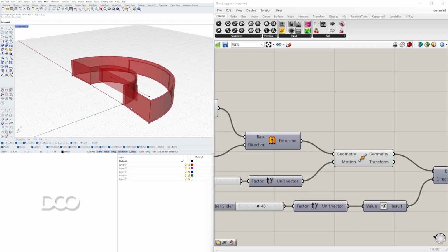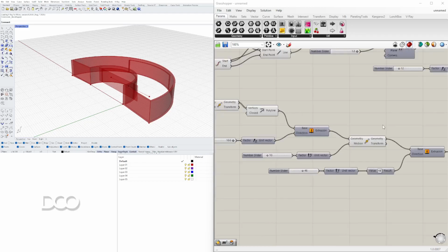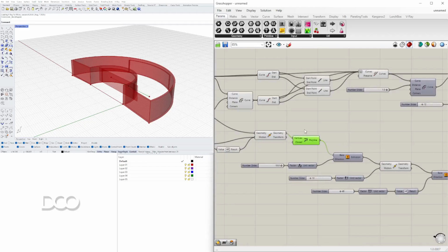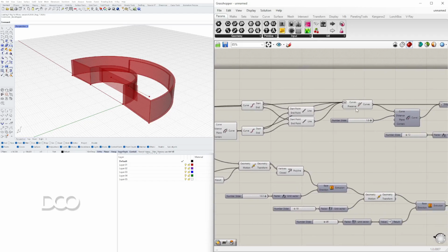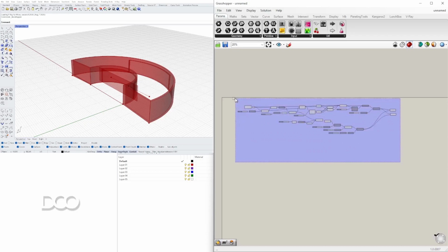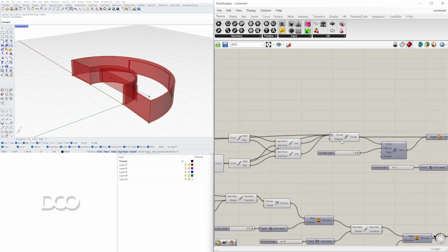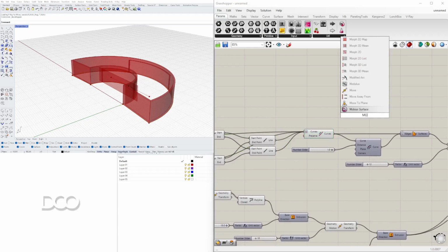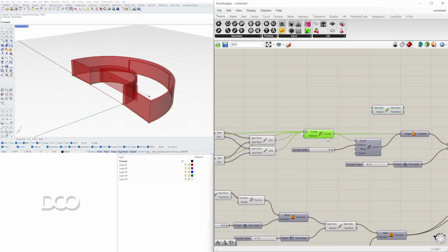On this next part, what we need to do is take that bottom outside line, bring it up, and then offset it to the outside to create a roof overhang. So we'll go back here to where we joined this base form curve. What I'll do is I'll give myself a little bit of room. So I'll take this and move this down. Then I can take this and move it up. So I'll go to move this curve in the Z direction. So I'll go to unit Z.